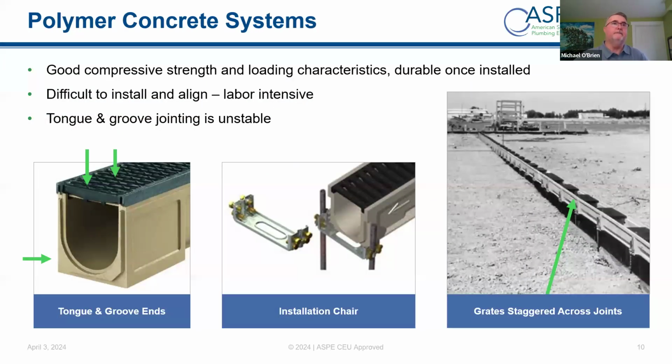These polymer concrete systems provide good compressive strength and loading characteristics once they're installed. But you can see here on the tongue and groove ends, it can be a little bit tricky to get those aligned and have them stay in place as you're running a full length. So there's an installation chair that the channels will sit on to kind of hold it in place, and then you stagger your grates across the joints to provide a little bit more integrity and to keep them from shifting as much as possible.